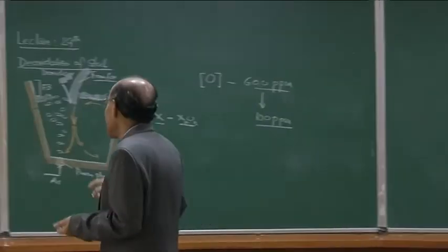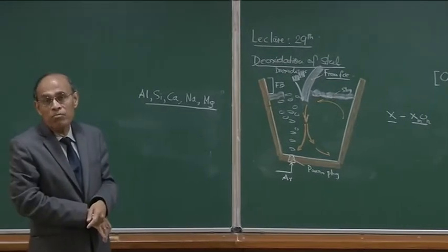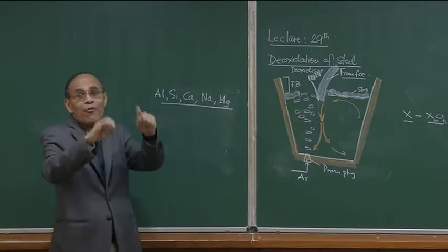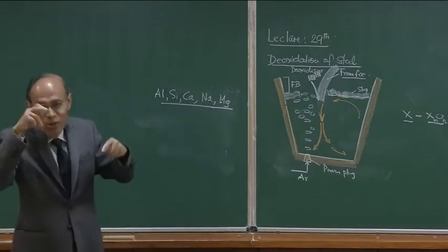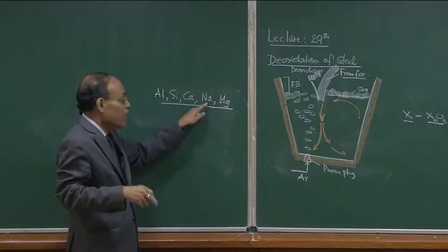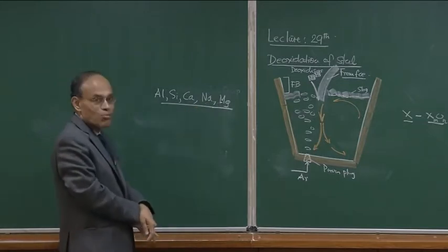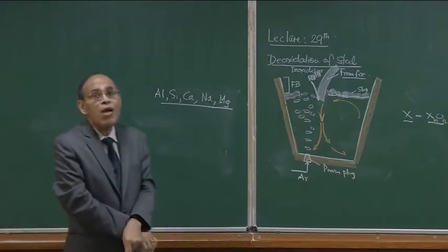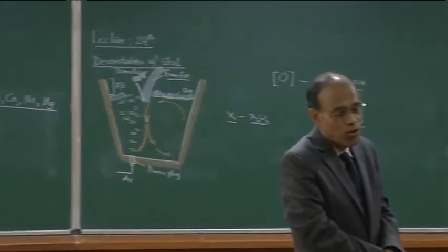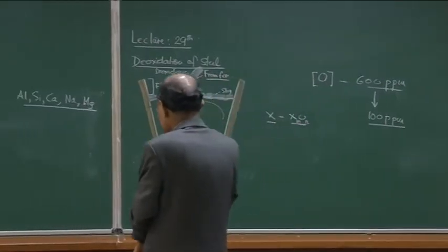For example, material like sodium will vaporize in no time, so it can be hazardous, and of course, most of the sodium you have added will be lost from the system. It will not dissolve into steel because of high vapor pressure and low boiling point. Bulk of the sodium will be lost without taking part in the deoxidation process itself. So, affinity towards oxygen is not the single criterion. The price is an important parameter, and the hazards of addition and their recovery are important considerations.